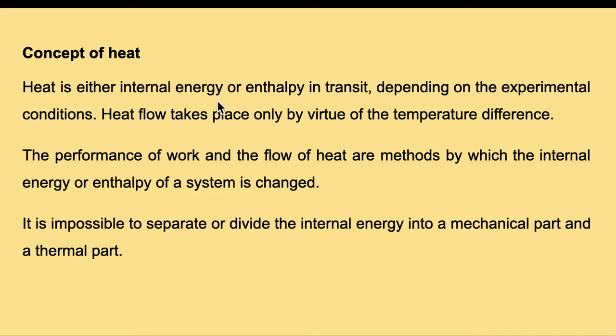Which quantity is flowing, internal energy or enthalpy? You already have the concept of enthalpy from chemistry, and in our coming chapters we will discuss that term H, enthalpy, known to you as U plus PV. We will deal with them later. Heat flow takes place only by virtue of the temperature difference, so that heat is either enthalpy flow or internal energy flow. And this is an important point.